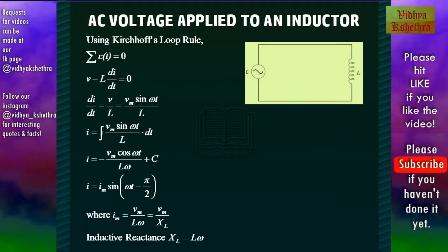Now using a trigonometric identity, we can write cos omega t as sin omega t minus pi by 2, and Vm by L omega as Im. Here L omega is equal to XL, or inductive reactance. This is a quantity which is analogous to resistance in the case of a resistor. Inductive reactance also has a unit of ohm.